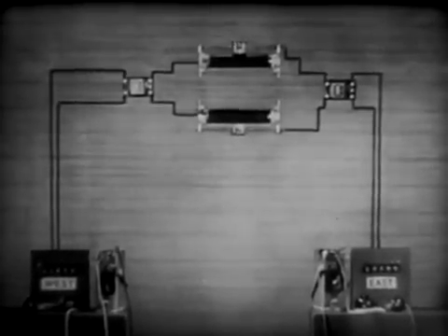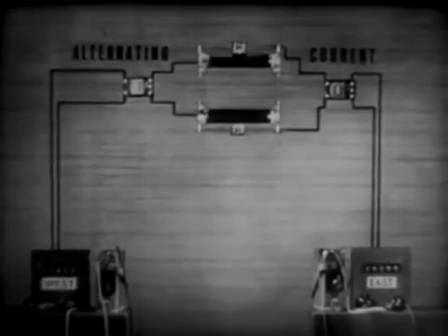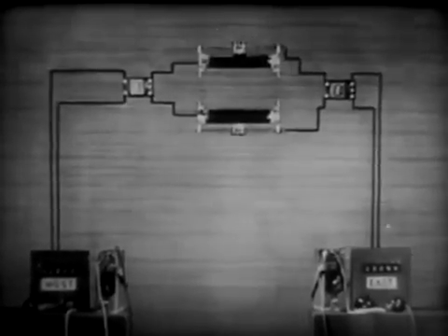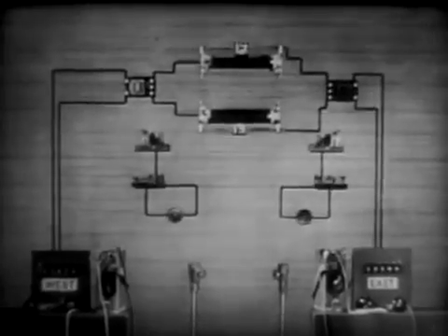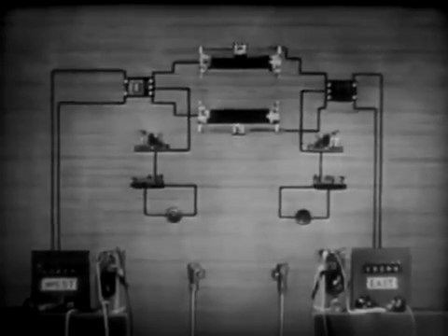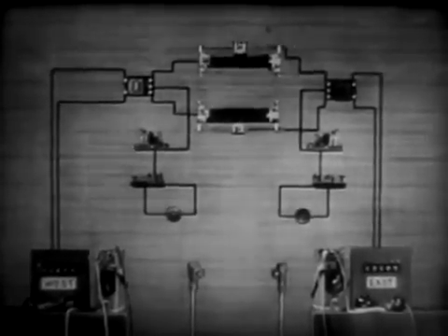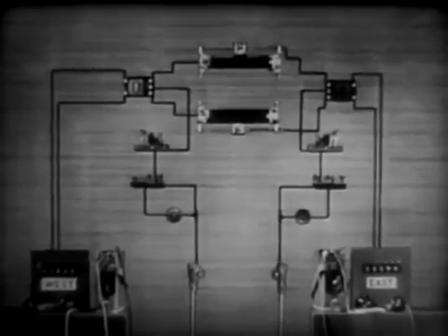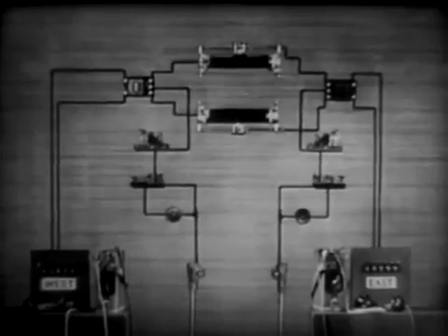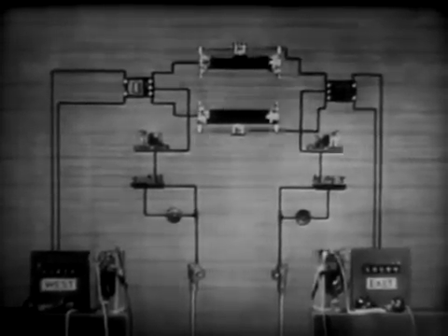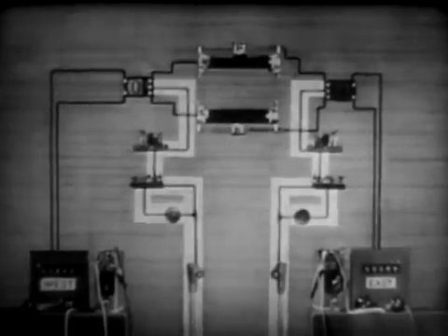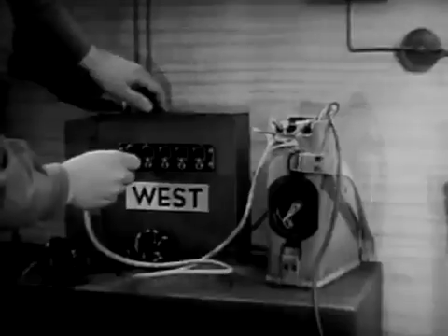We have seen that the coils repeat alternating or telephone current, so our telephone line is unaffected. Now we can connect a telegraph set to the midpoint of the line side winding of each repeating coil and complete the circuit through the earth. We have added the telegraph channel by using only a few extra feet of wire. The switchboards can still signal each other.